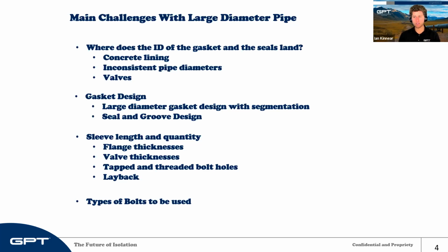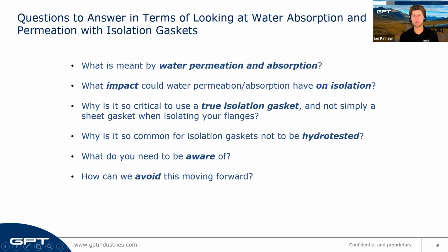Does the valve have tapped holes? That's something that we need to think about and account for. Is there inherent layback in the flange? And then lastly, an issue that I see more frequently than you would think, and I really just wanted to put it out there just to get some education, just to talk to you guys about it, is the type of bolts that are used in these cases. The last thing we want is for 60 of these 2-inch bolts or whatever it may be to be purchased on site to discover the sleeves don't fit. It's something we can avoid from the start, and it's a very expensive mistake when it does happen. So just want to bring some awareness to it.